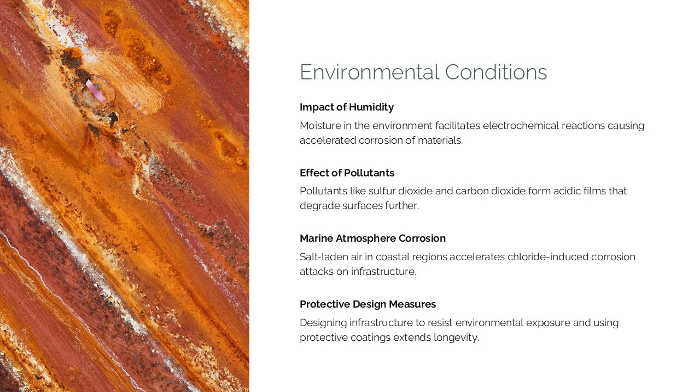Humidity, pollutants, and marine atmospheres significantly influence corrosion. Moisture facilitates electrochemical reactions, while pollutants like SO2 and CO2 form acidic films on surfaces. Salt-laden air in coastal regions accelerates chloride-induced attack. Designing for environmental exposure and implementing protective measures are critical for infrastructure longevity.